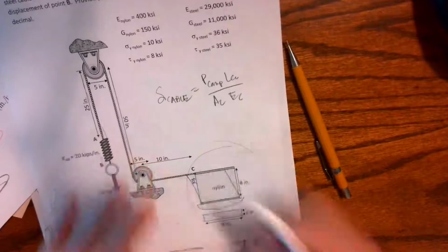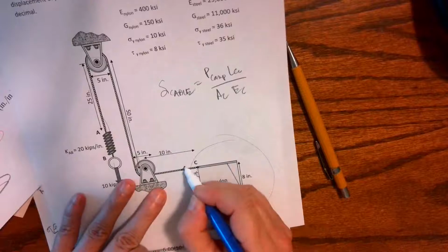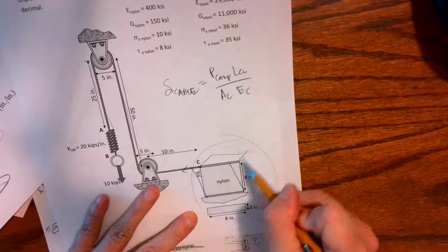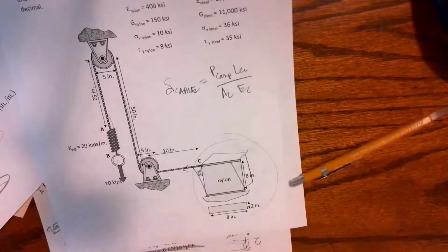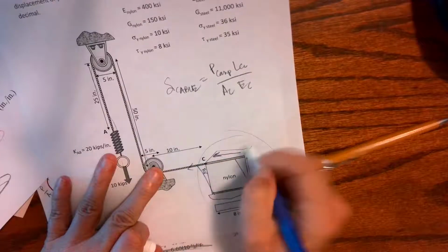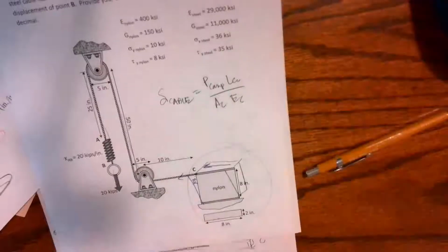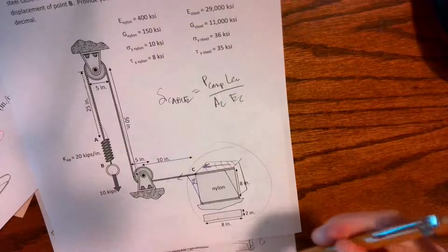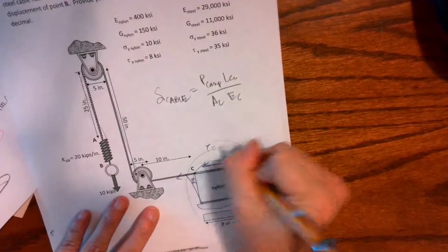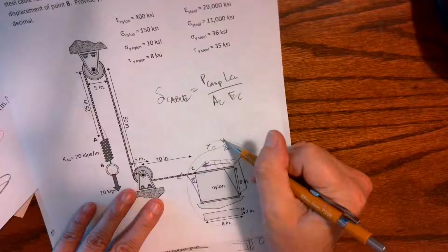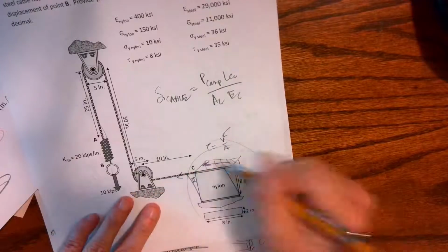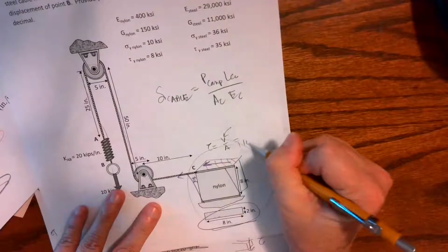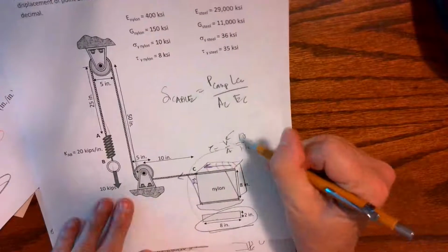Okay, so if I know the force that's here, and the block has a depth, there's the top of it, then this shear force is acting on the top of my block, then the area that it's acting on is this top. So this is just like, go back and review that quiz that we had. Shear stress is V over A. Okay, this V is the force in the cable. This A is, in this case, 16. And that V is 10 kips.